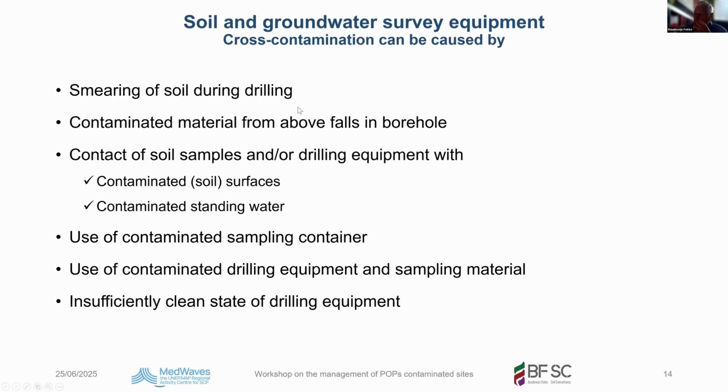Cross-contamination is when you have a sample and it's being influenced by other samples that are contaminated. So these samples are not representative anymore. Smearing of soil during drilling: you go through a contaminated layer and enter a clean layer, but your bore bit is not clean, and you take contaminated parts from your contaminated soil horizon to the clean horizon.